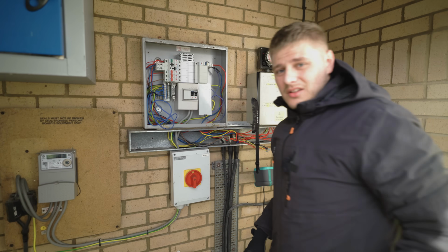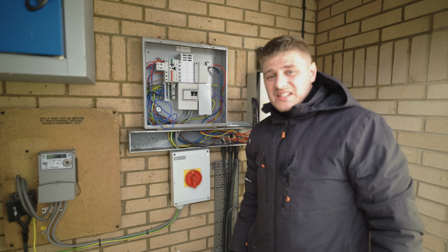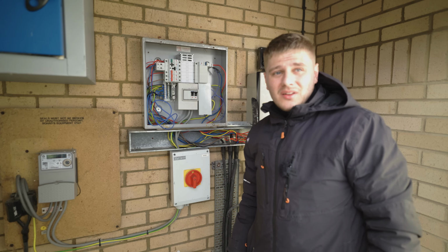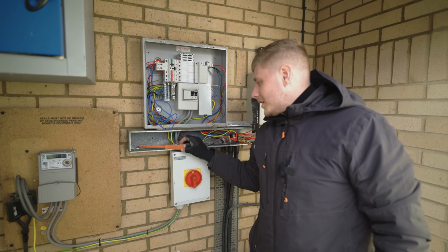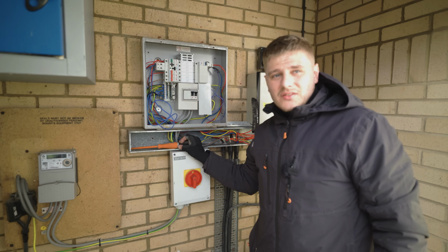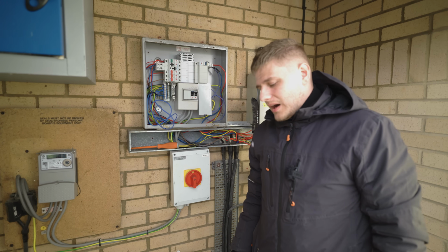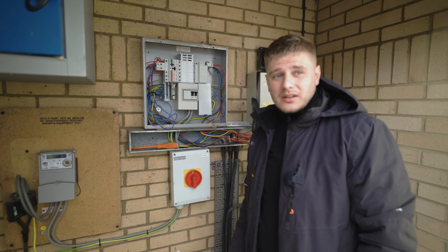Cool, so that lighting circuit's come on in a different breaker, just an MCB. It didn't like the RCBO, but in the MCB it's come on, which is interesting. And again, that's why the circuit passes as far as the insulation resistance test is concerned, but you know, the circuit's sound. Yeah, let's go see what lights are working and what ones aren't.